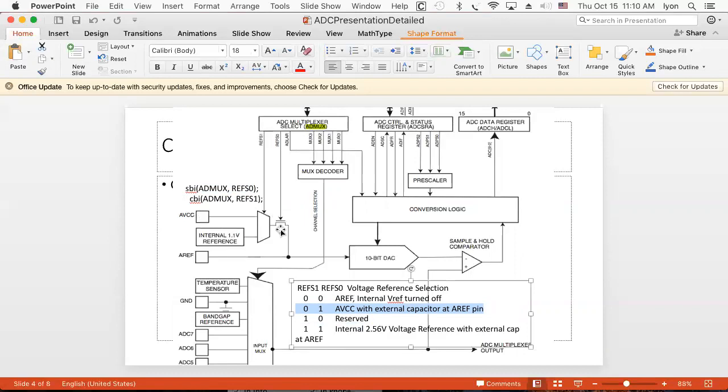to the DAC. So if we're not using an external capacitor, and we're not, then we are in the "we don't care, it's good enough for us" kind of camp. And that's all right if all you want to do is digitize an analog signal. But now you can see how the bits actually relate to underlying hardware and how they route signals around by setting up this little 0-1 versus 0-0 thing. So that's kind of cool, actually.